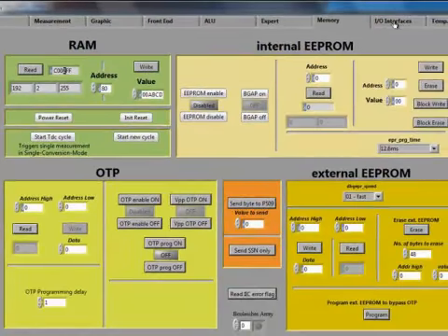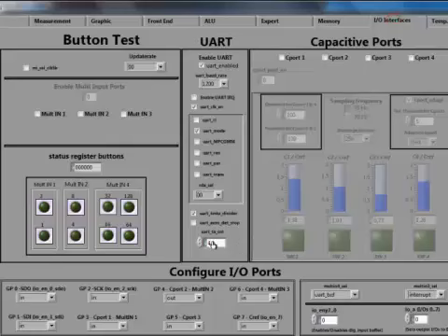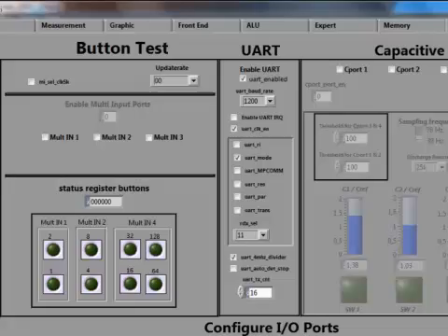Similarly, you can send up to 16 bytes in one go by setting the byte count here to 16 and then filling the bytes from RAM address 86 onwards. To receive using the UART, the same configurations as for transmit are valid. Additionally, the GPIO pin which has to be used as receive input has to be selected in this option here. On the evaluation board, reception only through GPIO 5 is possible. Hence, set this option to 3.